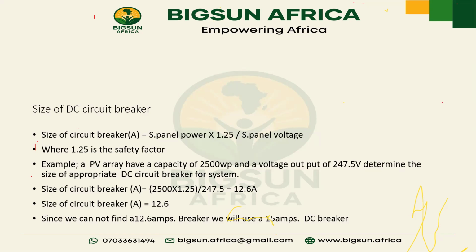So let's start from the obvious. If you have 9 pieces of 560 watt panel, to get your total power, you have to do 560 watts times 9, which is 5,040, right? Yes, sir.